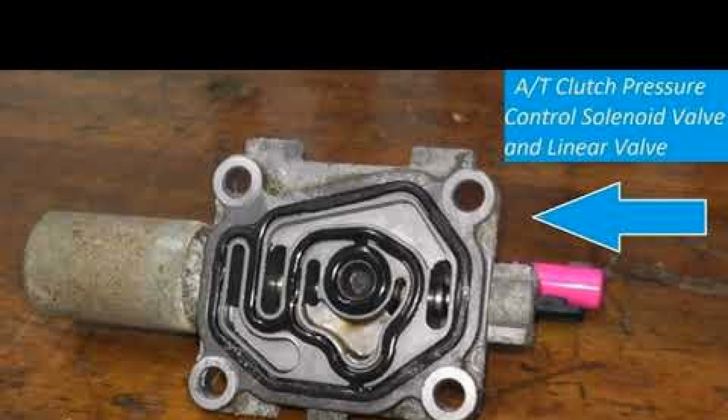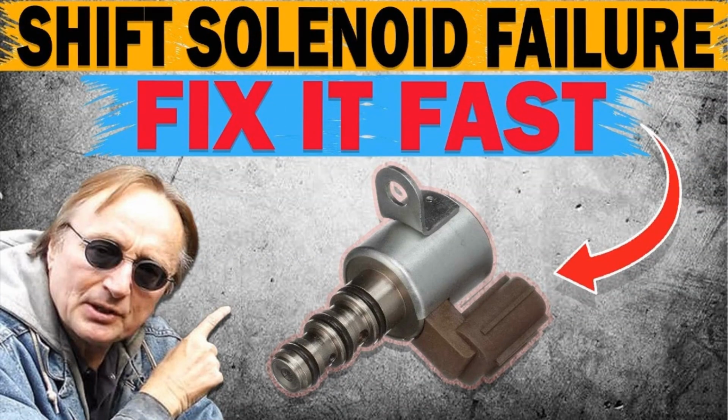Malfunction symptoms. The main P0796 fault symptom for the driver is the illuminated MIL, malfunction indicator light. This is also referred to as the check engine light. It can also manifest as the check engine indicator lamp on the control panel lighting up. The code will be stored in the ECM's memory as a fault.